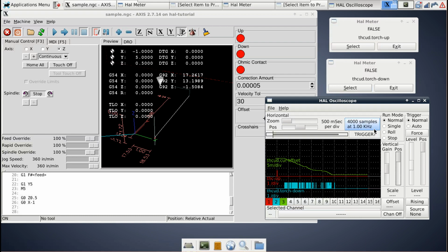And it's not like it gives you a massive plot of everything, but it gives you a short view of that moment where hopefully you can see what is going wonky with your CNC, right? You make it trigger at the moment you need, to catch that bug, and you can watch on every iteration of either your servo thread or your base thread what was happening and what signals were being received that made your machine do something that you weren't expecting.